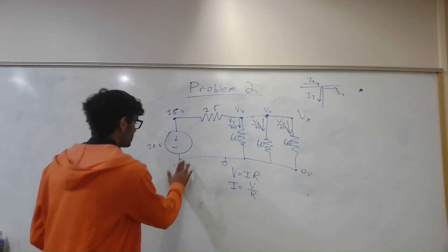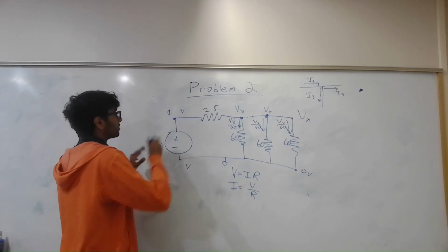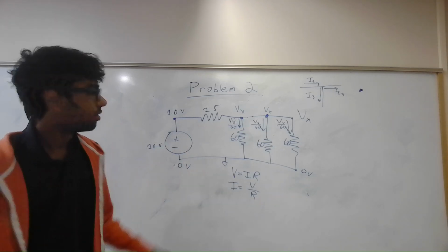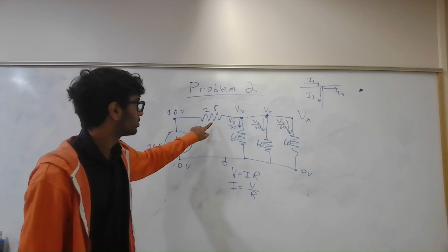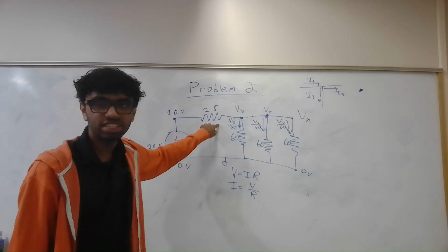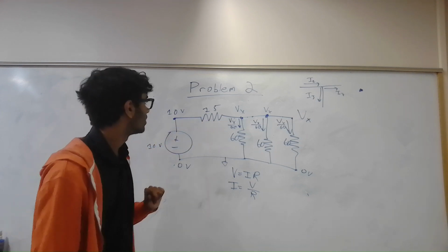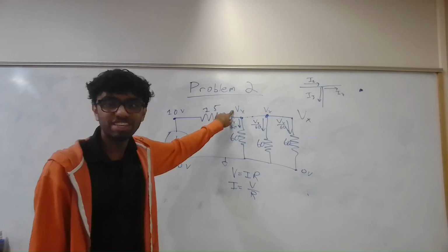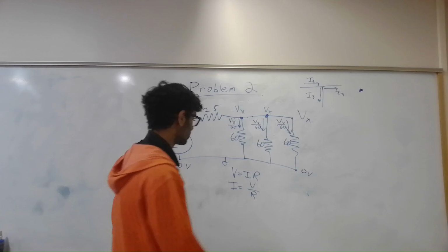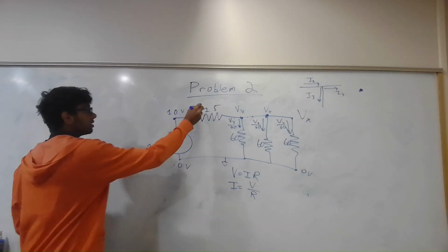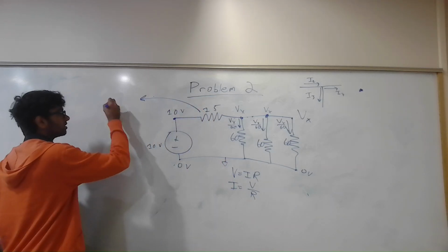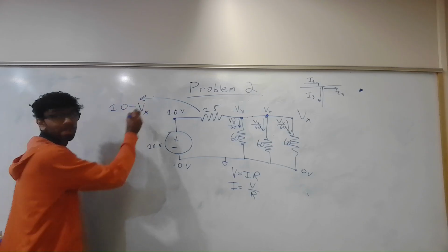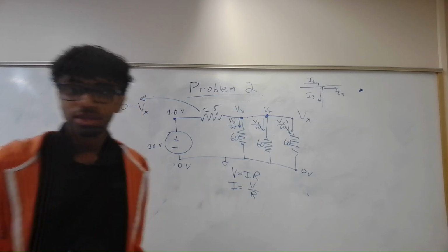And let's set these back to what we know those numbers are. We know it's 10 volts right here, and 0 volts right there. So what is the voltage dropped across this 15 ohm resistor? Well, if it's 10 volts before it and voltage Vx after it, the voltage dropped by that resistor is 10 minus Vx. Okay?